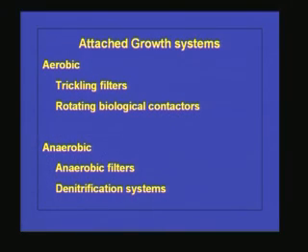suspended growth systems. So today we will discuss attached growth systems which are commonly used in wastewater treatment, that too in aerobic conditions. So coming to the attached growth systems, the most commonly used ones in wastewater treatment are trickling filters and rotating biological contactors. There are a few other systems which are not so commonly used, but are coming up in wastewater treatment processes. They are fluidized bed attached systems and submerged systems.